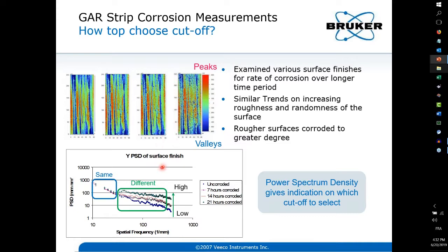Well, these defects will be nicely spotted by what we call power spectral density. And this is the so-called PSD graph. And PSD is no more no less than plotting the roughness for a given spatial frequency. So we can see the roughness variations as per the spatial frequency, so as per the size of the details.